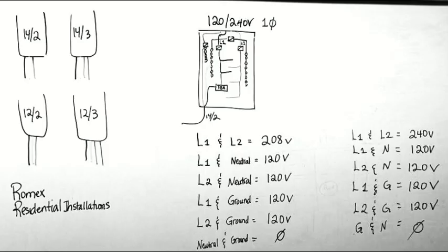We have a red wire, which could be a current carrying conductor, a black wire that could be a current carrying conductor, a neutral, and a bare wire that is for safety to connect every metal part of the circuit. And we go further to larger wires. So for example here, we have a number 10. We have a 10-3. This 10-3 has a black current carrying conductor, a red current carrying conductor, a white as a neutral, and our bare wire for safety, right? But this one, what capacity do we have in amperage for a number 10?